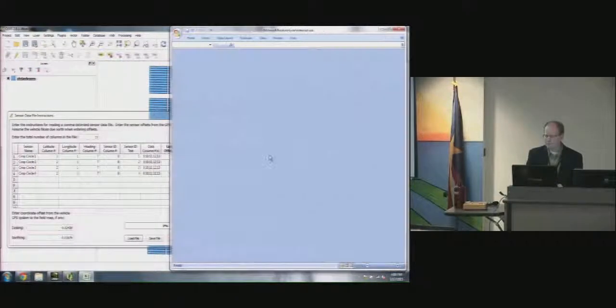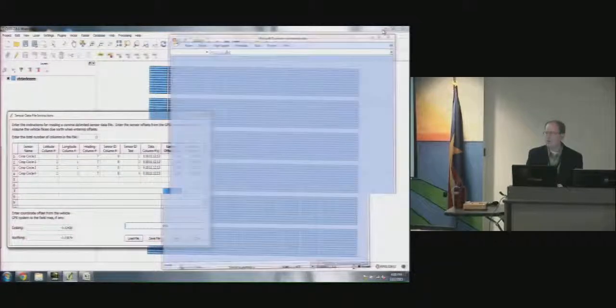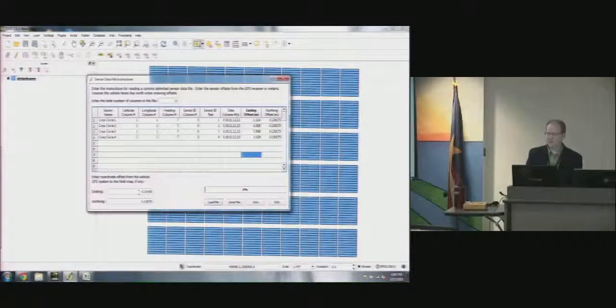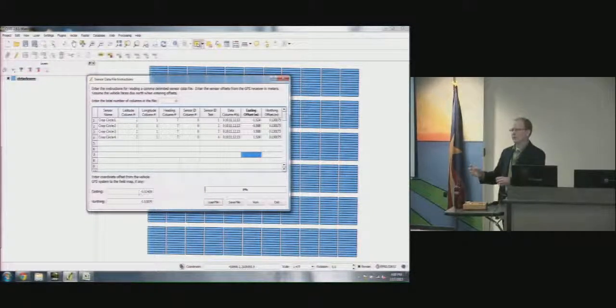So when you measure the easting and northing numbers for the bottom corner, you just go to the same exact reference point with the 2 systems and see what their offset is. Well, no, you just have to put them at the same location. Take both systems out and put the rover receivers at the same point and let them collect some data for an hour or 2. And from there you can estimate what is the offset between the 2.